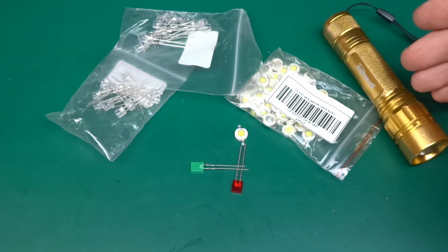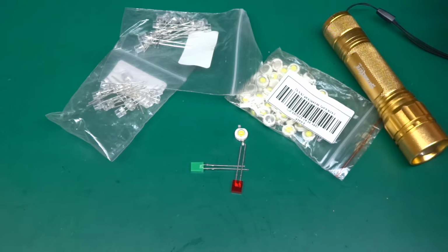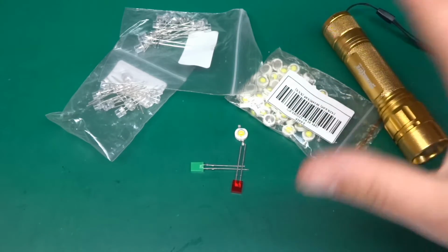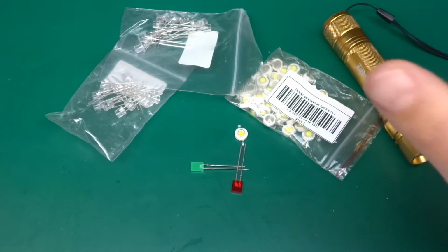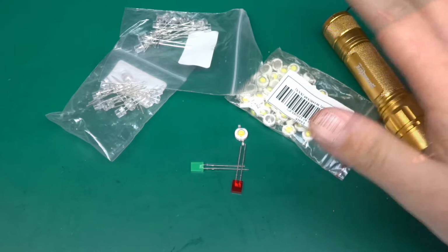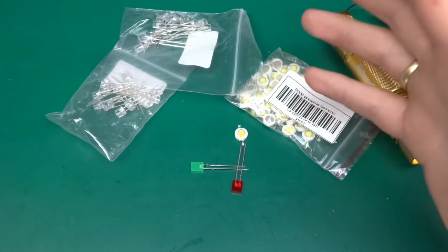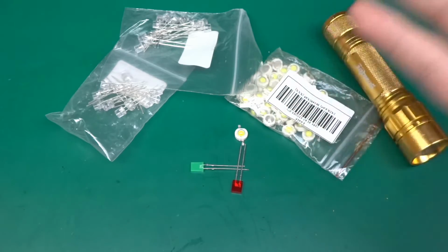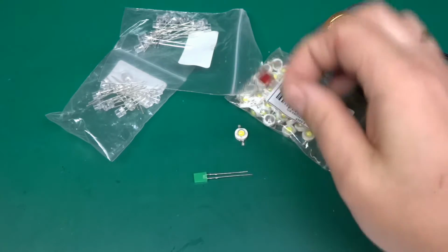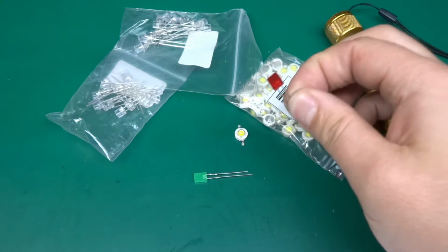Then you're going to check the continuity on the LED, and it's showing infinite resistance, and you think the LED is busted. That is not the case. So let me show you a quick and dirty way to check a few LEDs, even if you haven't got a multimeter. It's a really simple way, and also a common mistake that happens when you're trying to measure an LED, because it's a little bit counterintuitive, but an LED, a diode, is a non-linear element.